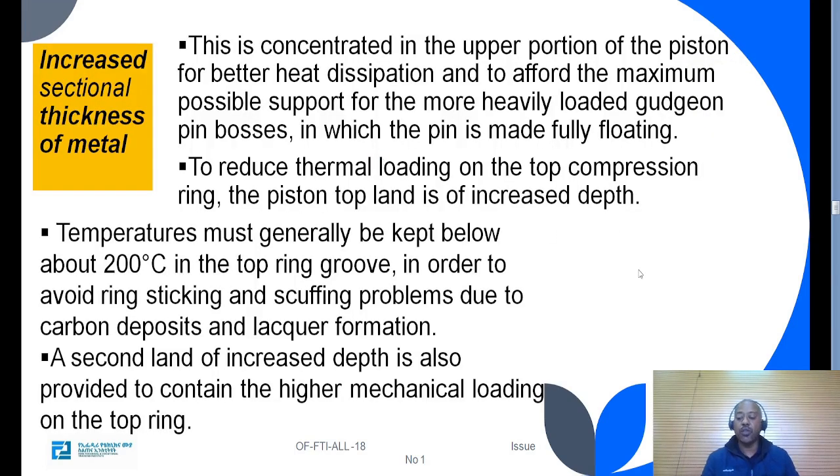Increased sectional thickness of metal. This is concentrated in the upper portion of the piston for better heat dissipation and to afford the maximum possible support for the more heavily loaded gudgeon pin boss, in which the pin is made fully floating. To reduce thermal loading on the top compression ring, the piston top land is of increased depth.